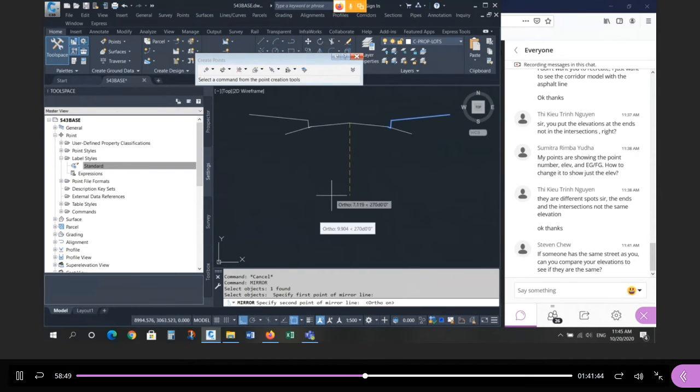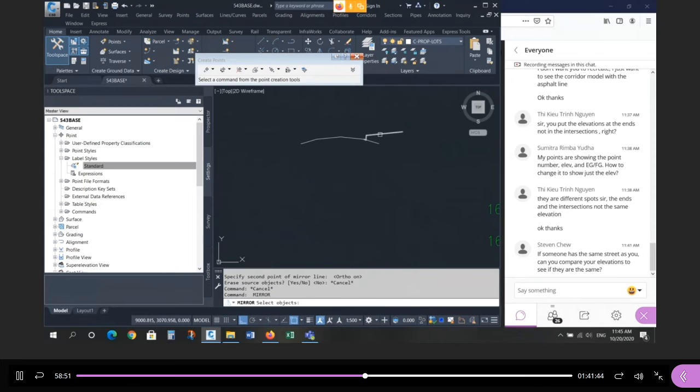And the one on the other side. So in the future, this curb and gutter is going to match the edge of asphalt. So that's what it wants to look like eventually. We're going to keep the asphalt in the middle, and we're going to get rid of the shoulder and the ditches, and we're going to have a full section like that.